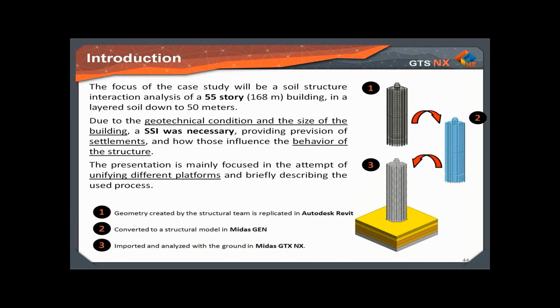So the building, which is the focus of the presentation, is a 55-story, about 168 meters tall, designed in a layered soil of low resistance. And because of the size of the building and the soil-bounded site, soil structure interaction was necessary to evaluate the settlement and the behavior of the structure.